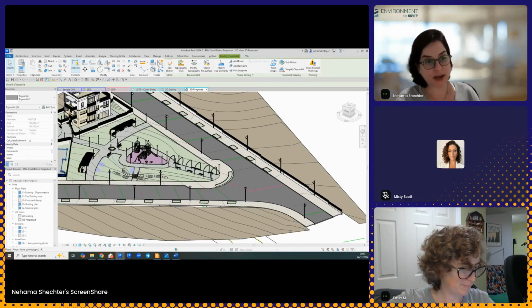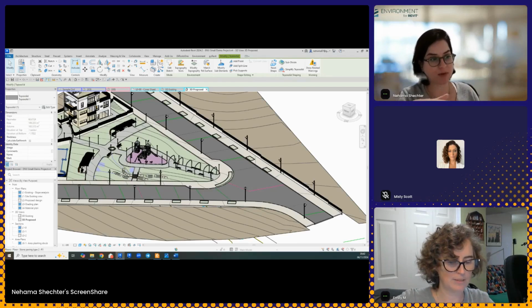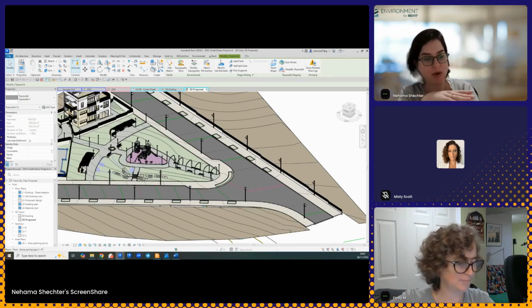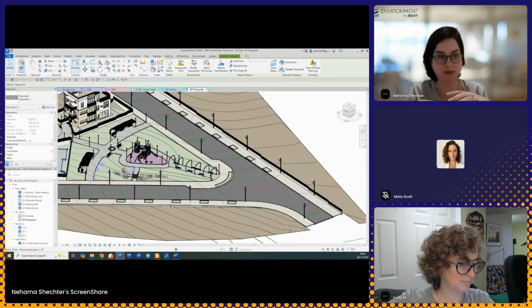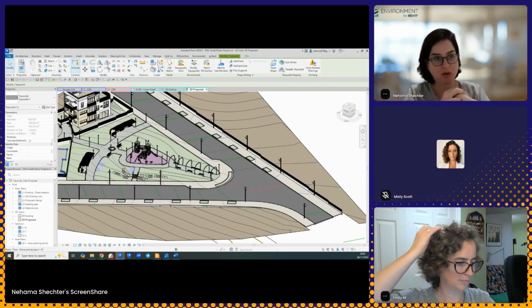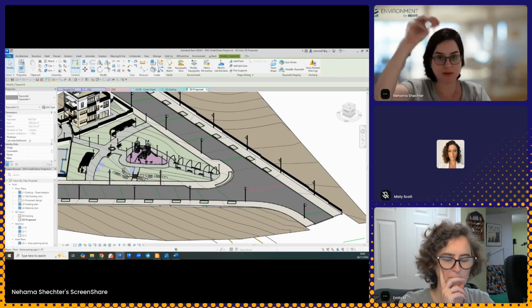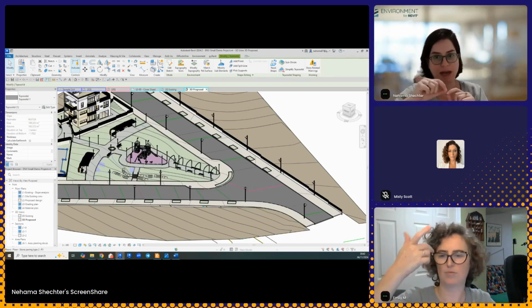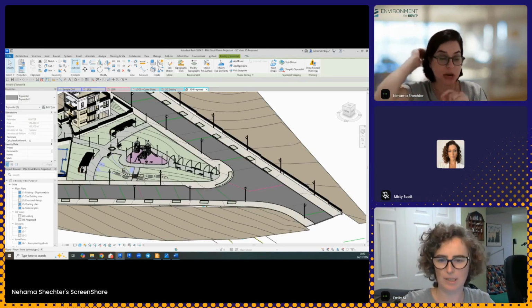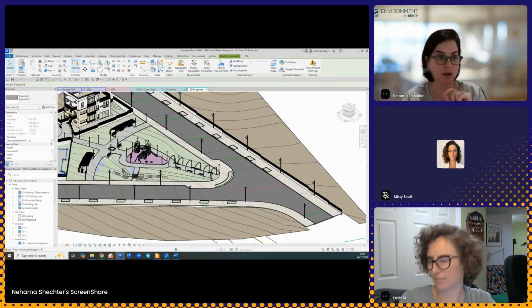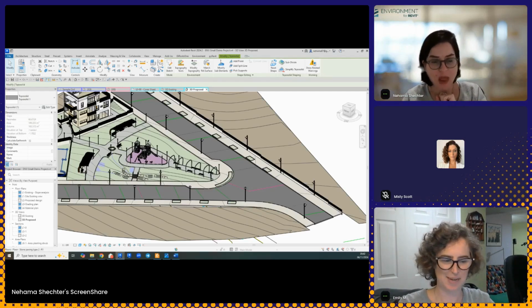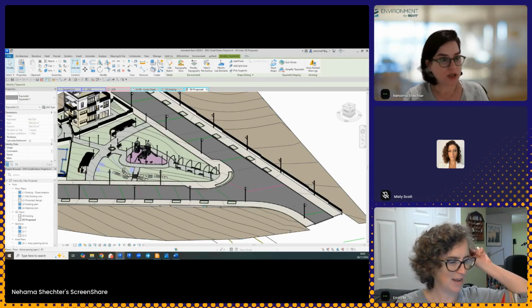I think specifically in AutoCAD, if you don't do anything, then everything is at sea level. So if your Revit file has a level that's defined as sea level and it's down in the survey point, and then you import this AutoCAD file and you don't have elevation in AutoCAD, it will fall at sea level. And then if you give them elevation in AutoCAD, then it will be an absolute elevation relative to the sea level. That's how I understand AutoCAD works. But again, I'm not the authority for AutoCAD. Gladly. Yep. Any other question?